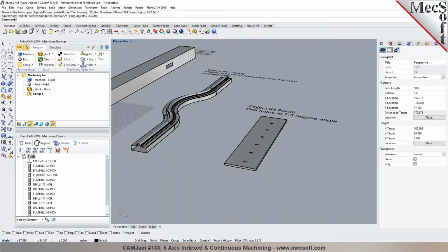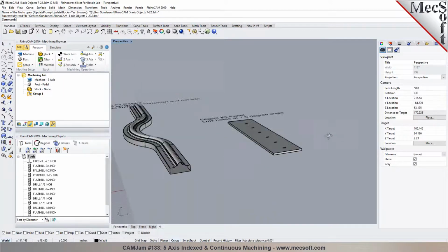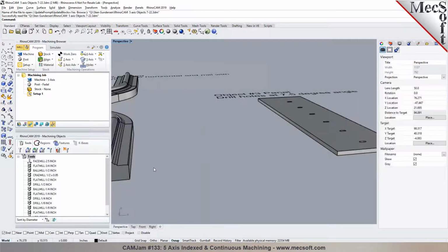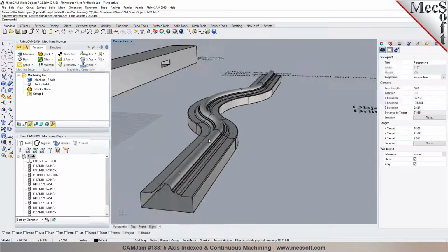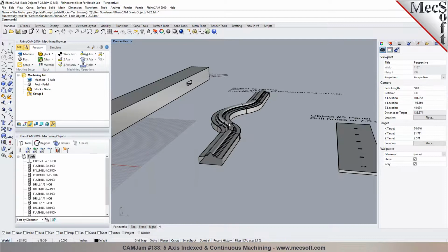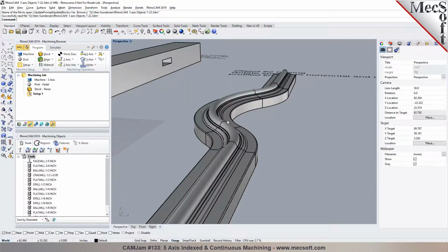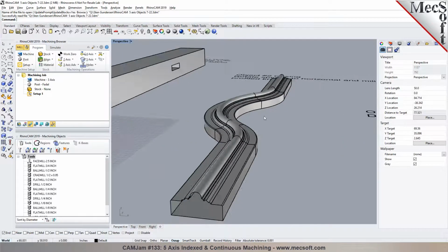Okay. So in this case, it wouldn't be two-axis, because if the head is rotated, then over here Z would be varying, right? Because if the tool is parallel or perpendicular to this face, then it's basically a Z-axis motion. The cutter would be going in and out as you're following this bend over here. Yes, I believe we're saying the same thing. Okay. So in that case, you can do an engraving operation, which can follow along a 3D curve.